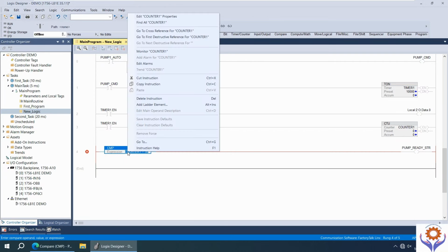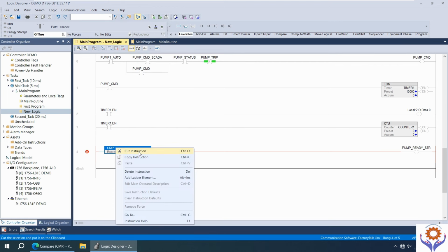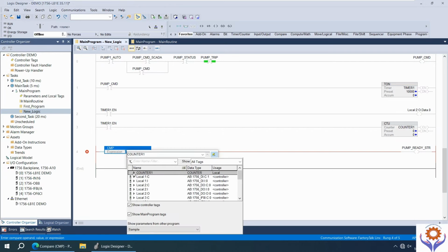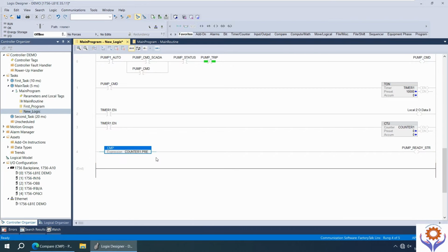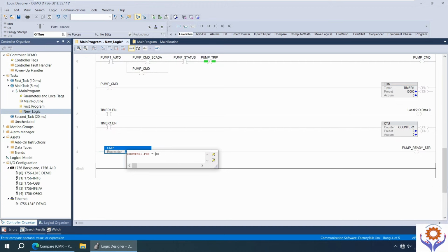See, now there is no error because in the counter block you have only PRE and accumulator. These two only you can utilize in your comparison block. You cannot utilize the other functions because the others are only booleans. See, now I already added the preset or accumulator, and I get no error. So you need to understand first, you have to study your instruction. Once it's okay, you cannot find any error, I compile this application, I don't have any errors, so I can utilize this application now.